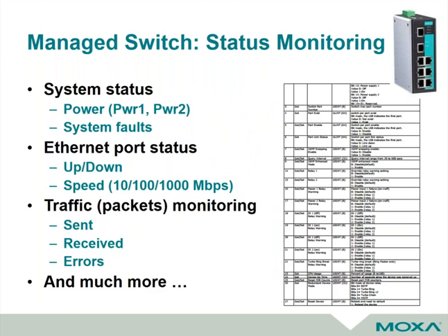So if you were to take, for example, a managed switch, remember managed switches have a secondary processor inside, and they're able to actually do a lot of things to monitor what's happening on your network and control network traffic. If any of you are using EtherNet/IP on a network, you know how important IGMP query and snooping is for performance. One of the least understood things is all of the data that can be collected by those switches and how you can get it. Here's an example of a lot of objects that are a standard, and we call this a MIB, or management information base, part of the database of information that's out there that you can pull.